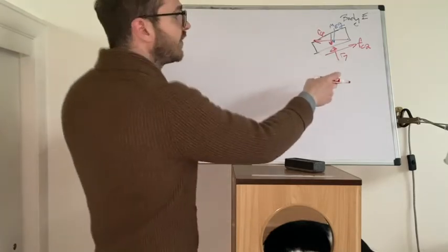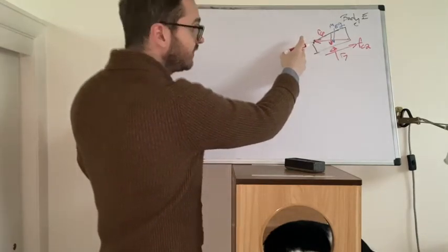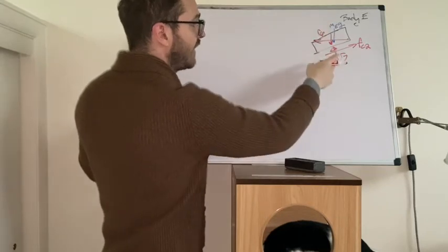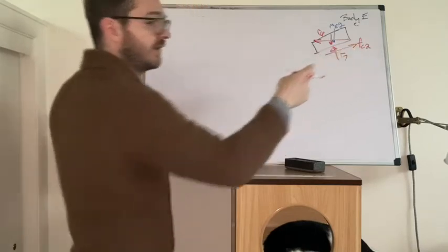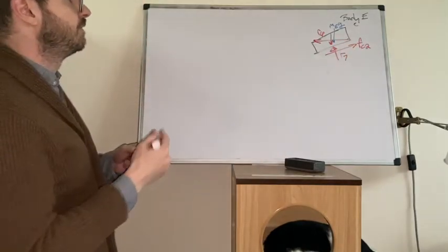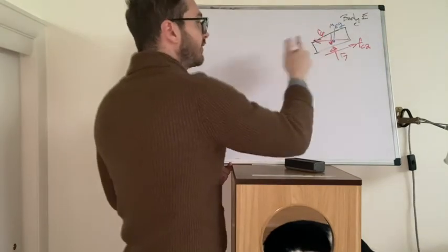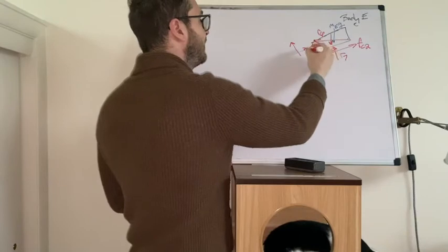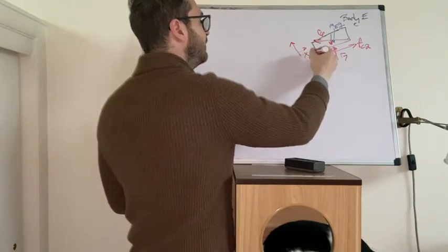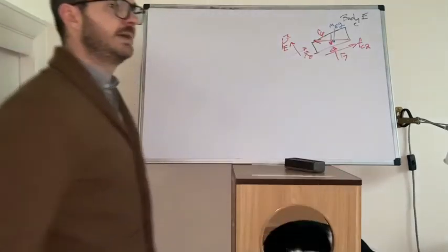All right, everyone, last one, body E. Here's the free body diagram for it. Remember, there was reaction force set number 6 from the last pin joint. It has its own gravity. There's a normal force, R7, and there is a Coulomb force, number 2. Now, this block is moving along a slope. Let's draw the frame for the body itself to help us out. Here is XE, and this other one is YE.